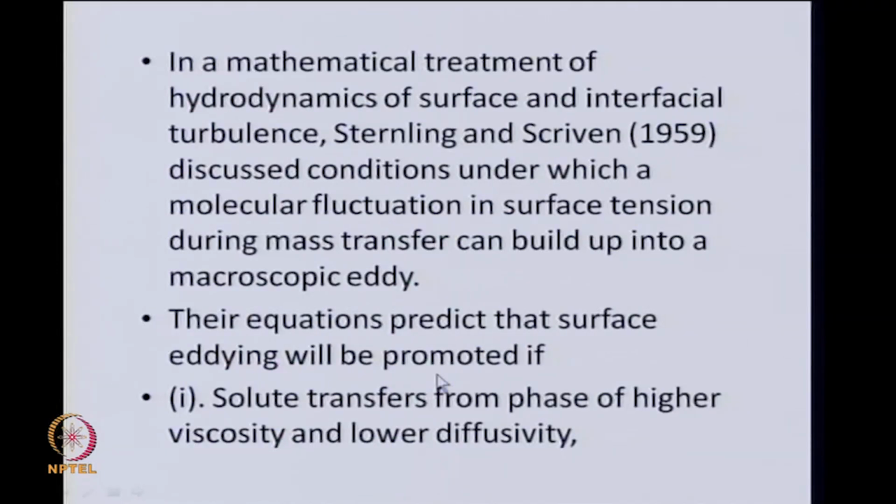is that eddying will be promoted if several of these factors are prevalent. First, the solute transfers from a phase of higher viscosity and lower diffusivity into a phase of lower viscosity and correspondingly higher diffusivity. So, our example here, I will try to benchmark against these statements. It is now an ether water solution, that is a phase of higher viscosity, there the diffusivity of ether will be lower. In general, in liquid phase the viscosity and diffusivity will be inversely related, right.